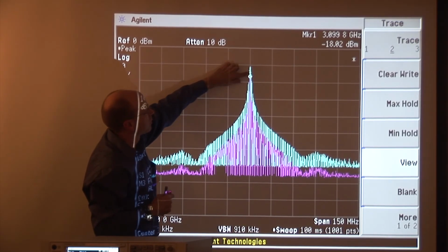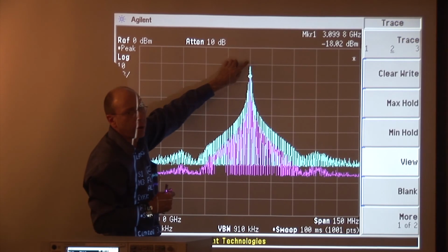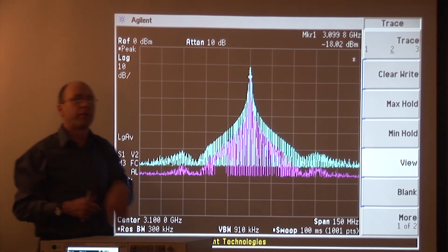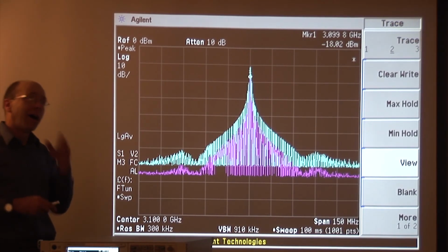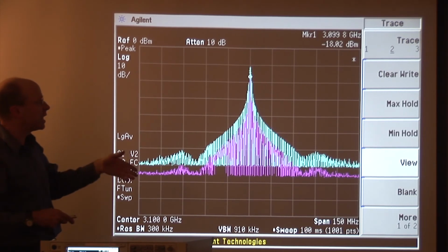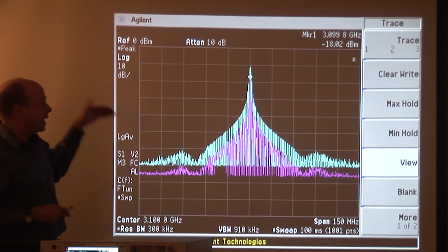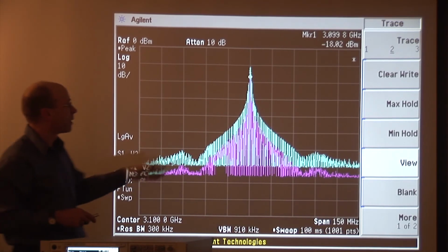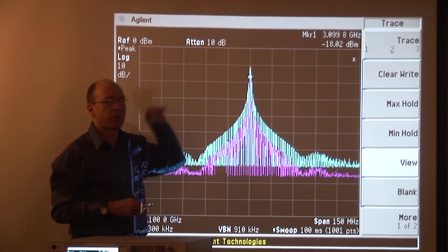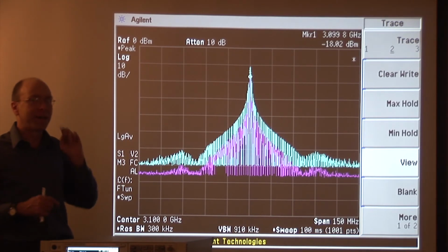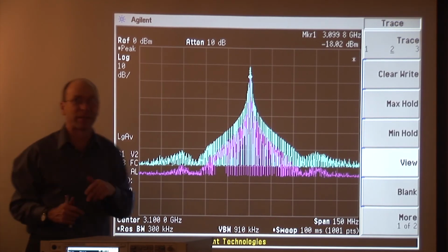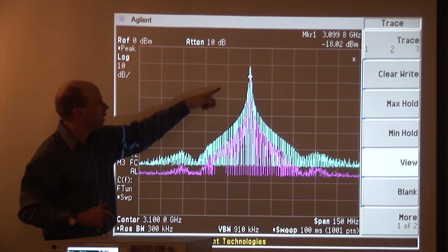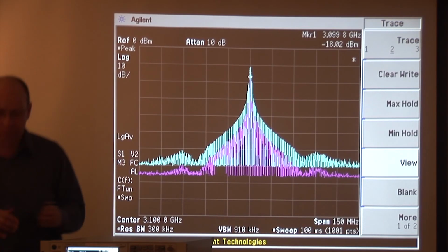For the 1 megahertz measurement, we put the top of the mask here, but then we draw the mask down from there. So if we want to check compliance with the mask, operationally or functionally speaking, we can at least get consistent results from one spectrum to the next in terms of how they fit the mask by measuring a bandwidth that's equal to or less than 1 over the pulse width, but not greater than 1 over the pulse width.